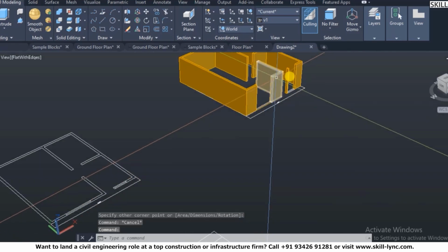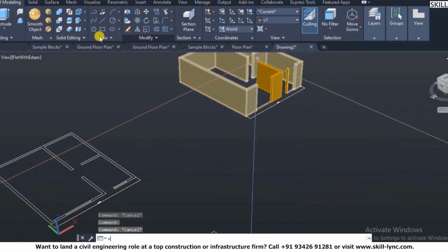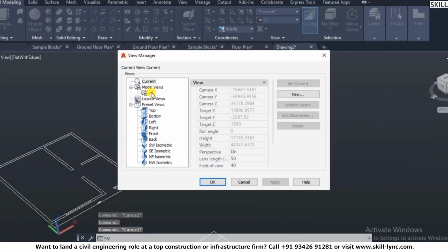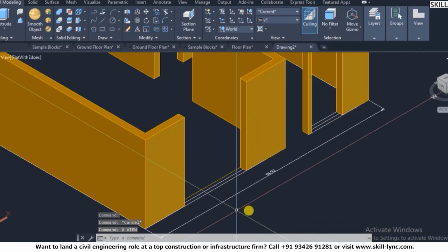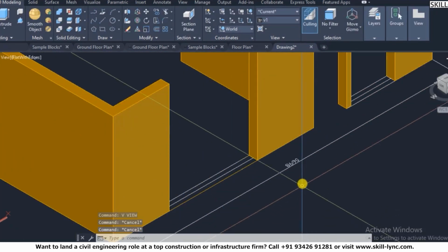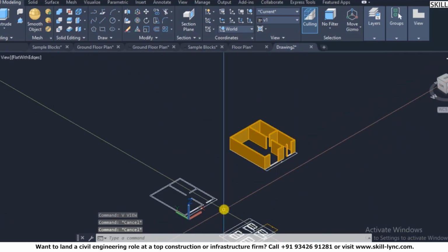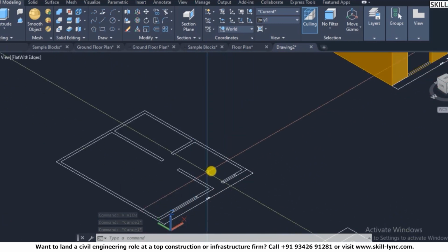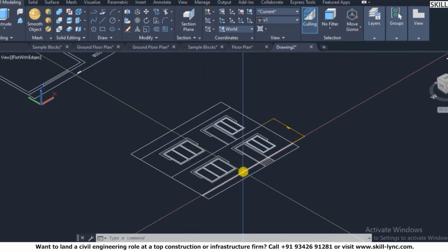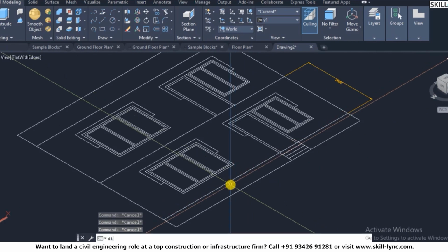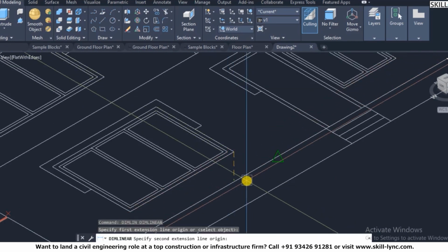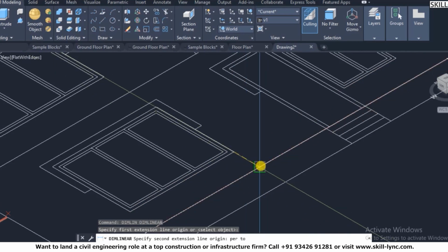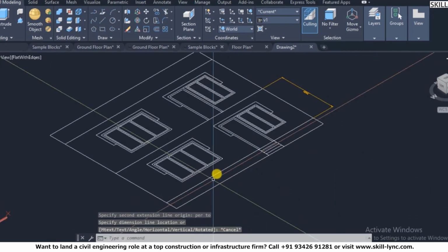The next thing that I would do is, so V is this, and V1. Okay. The next what I would do is, I would move this. Let's say, for example, first of all I would like to find out the sill level of this. So here, to find out the sill level, I need to go to my plan and see the sill level is 600.